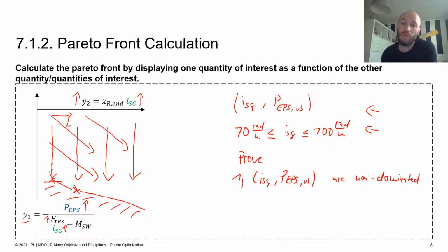With this we prove that our derived designs are at least part of the Pareto front. And in the second step we prove that only those designs within our derivation are the Pareto front, so we are not excluding anything. This can be done by showing that all other designs, which are not covered by the gear ratios and the upper bound of the power of the actuator, are indeed dominated.